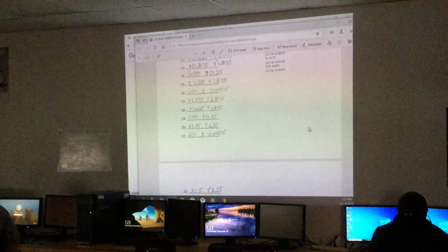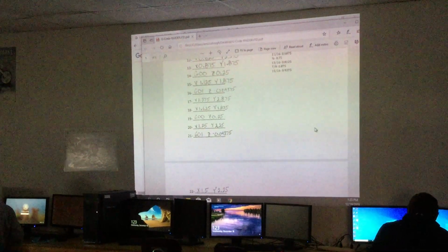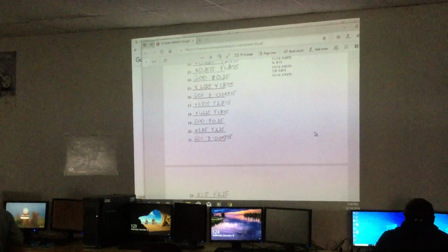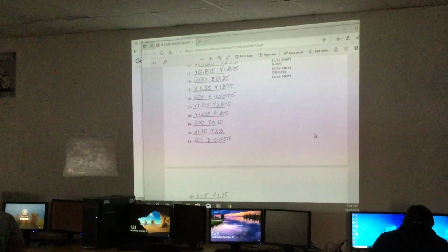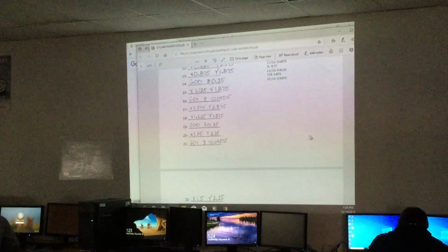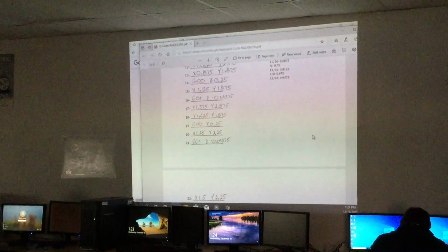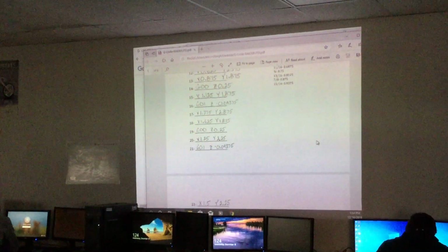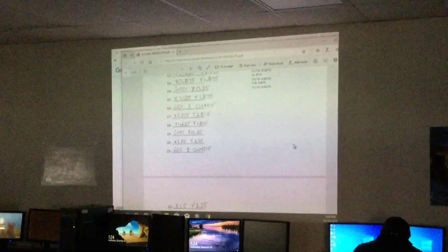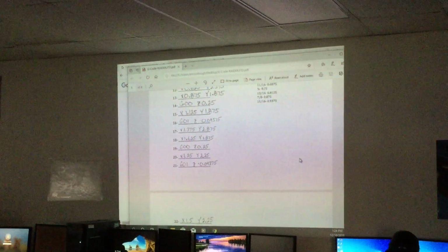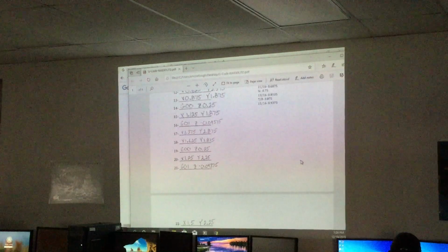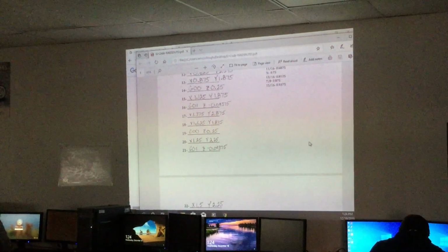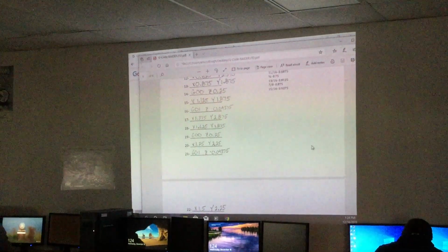And when we first started doing this, we were just putting 1. That was taking a long time too, because it was going up all the way to 1. Why does it need to go up to 1? It doesn't. You just want it out of the material to where you can cut as fast as you can. You want it to look nice, but you want your production to be as quick as possible. So at step 14, we raise it up. Then step 15, what did I tell it? Yep, 1/4 inch. And then step 16, I did what?